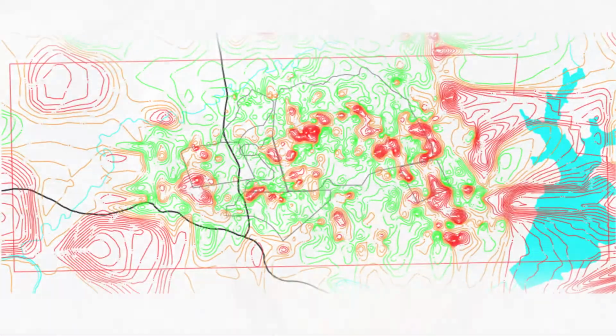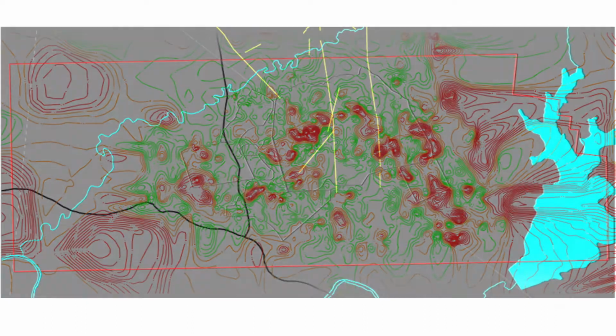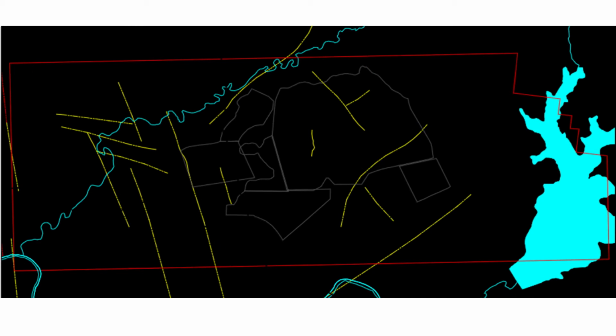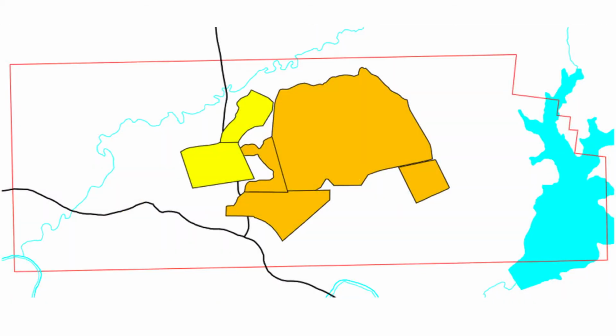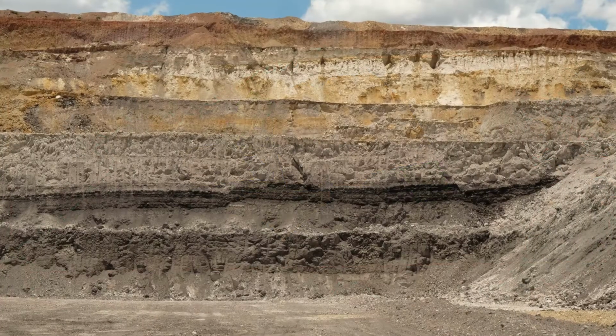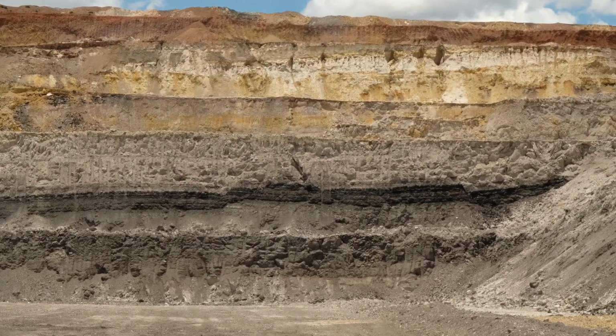Using the geological, hydrogeological, structural, geomechanical and spatial data described in the previous sections, the geotechnical engineer will define geotechnical domains. Geotechnical domains are areas or zones that have similar geotechnical characteristics and are not necessarily defined by lithological boundaries. Determine range of rock mass and defect strengths.